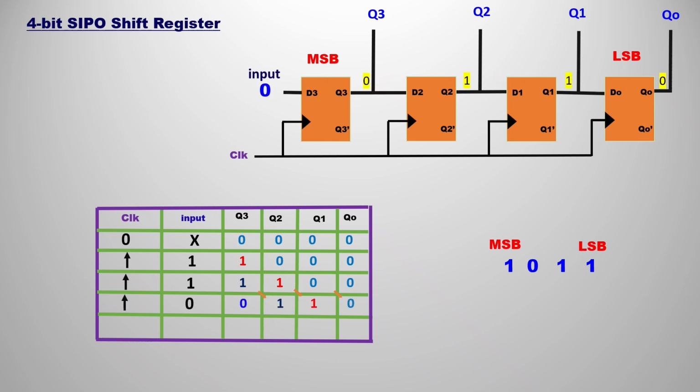The next input you are going to pass to D3 is 0. After passing 0 to D3, you can observe a movement towards the right. If you see clearly, Q0 is gradually popping out, meaning the zeros are popping out gradually. Finally, the last one, that is the MSB, we are also going to pass as 1.